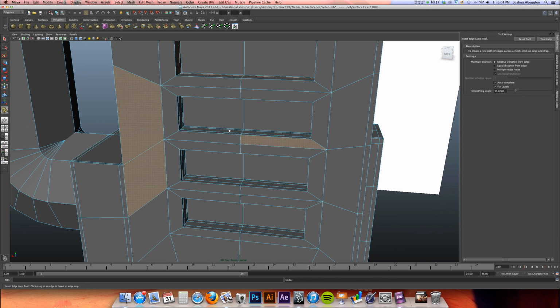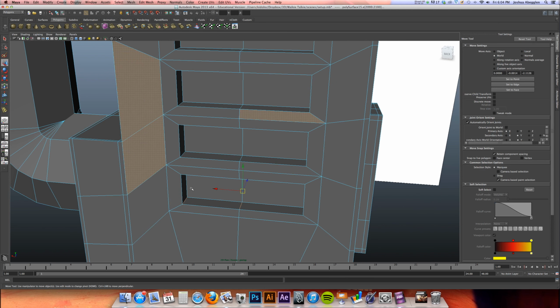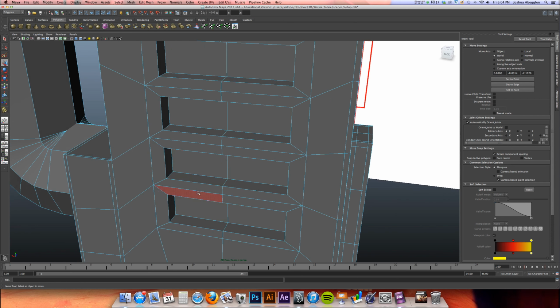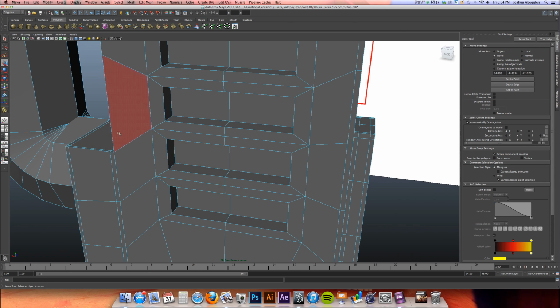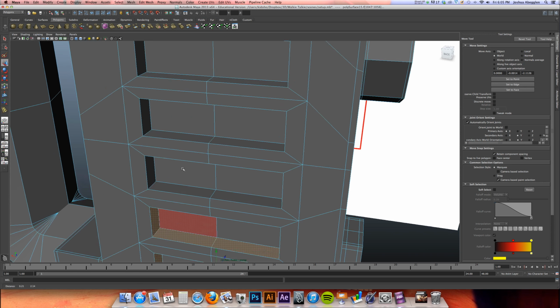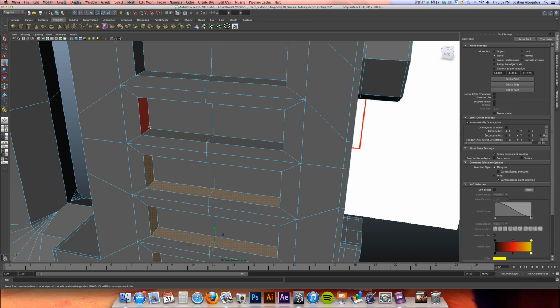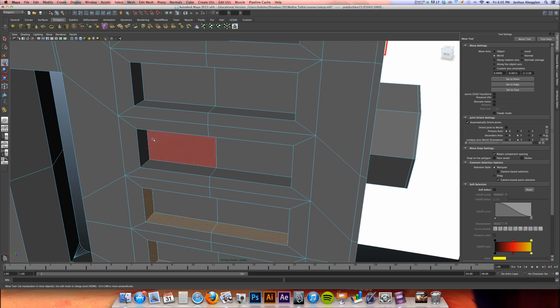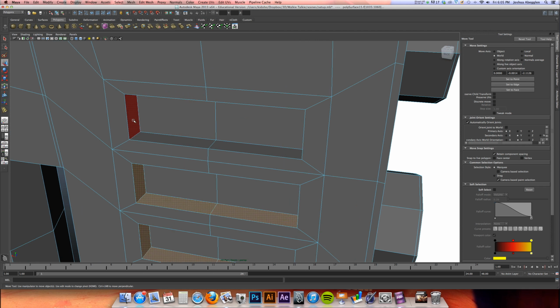Let me back up real fast. I've got an easier way of doing this than manually inserting each one of these edge loops. Let's come into, select this in object mode. All right, I was trying to do that to purge this few selected faces over here. Let's actually select the edge flow. It goes around the indentation for each one of these buttons. And then what we can do is use the Cut Faces tool on these faces only.